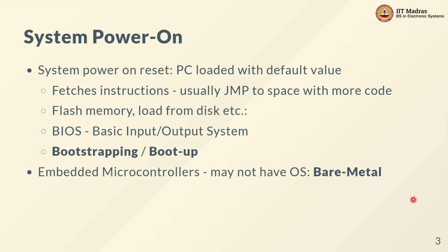In principle, yes, but I could also argue that the megabytes and gigabytes of RAM present in the system don't really contribute anything meaningful to the state of the system as such, especially at boot up time. On the other hand, things like the program counter and the state of some of the internal registers are directly related to the state of the processor. And in fact, they directly influence what's going to happen next when the processor switches on and the clock starts ticking from that point onwards.